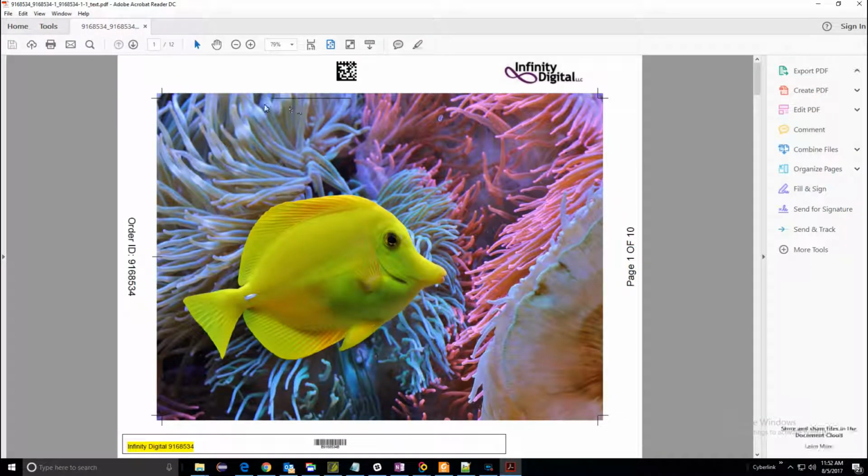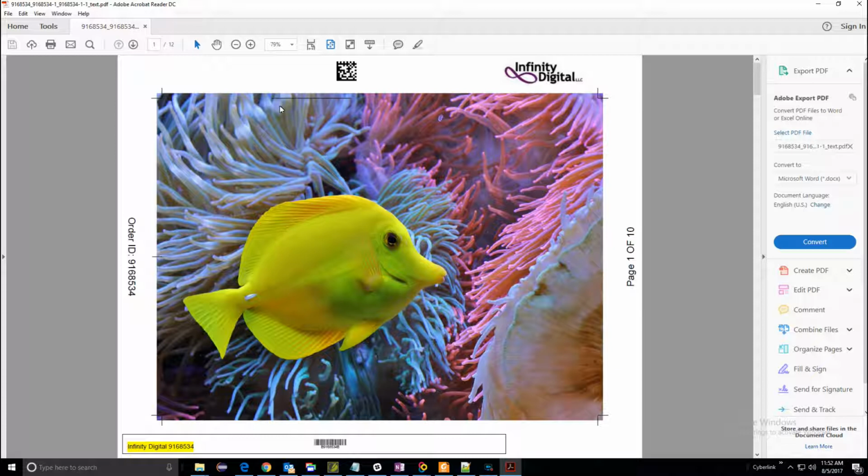And right up here at the top we can see this mark. Since we told it to lay down a trim mark and our side was relative to the top, a trim mark is going to go parallel to that side that we're working with. So it's going in the same direction parallel to that top edge. Compare that to the cut mark, which we said was side left. That mark is going perpendicular to the side that we're dealing with. So depending upon which element you choose, a cut mark or a trim mark, and which side you are relative to for that mark, the lines could be going one of two directions, either parallel to the edge or perpendicular to the edge.